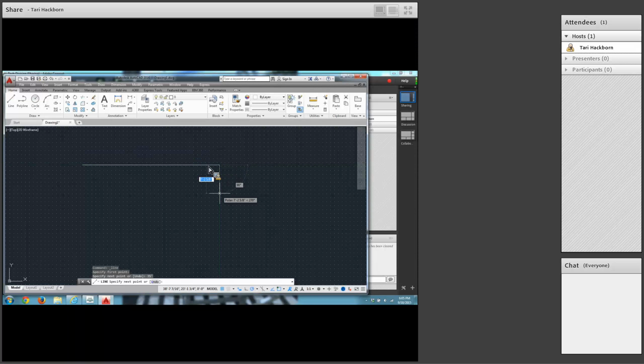and in the book the dimension says 25 feet 5 inches. To enter that information so that AutoCAD understands it, type 25 single quote and then no space and just a 5. You don't need the inch sign. AutoCAD assumes inches. When you enter the information for AutoCAD, you won't put hyphens between feet and inches. If you apply a dimension using a dimensioning tool, then it'll have a hyphen. Entering it for AutoCAD, you'd only use the hyphen if you're adding a fraction after the inches.